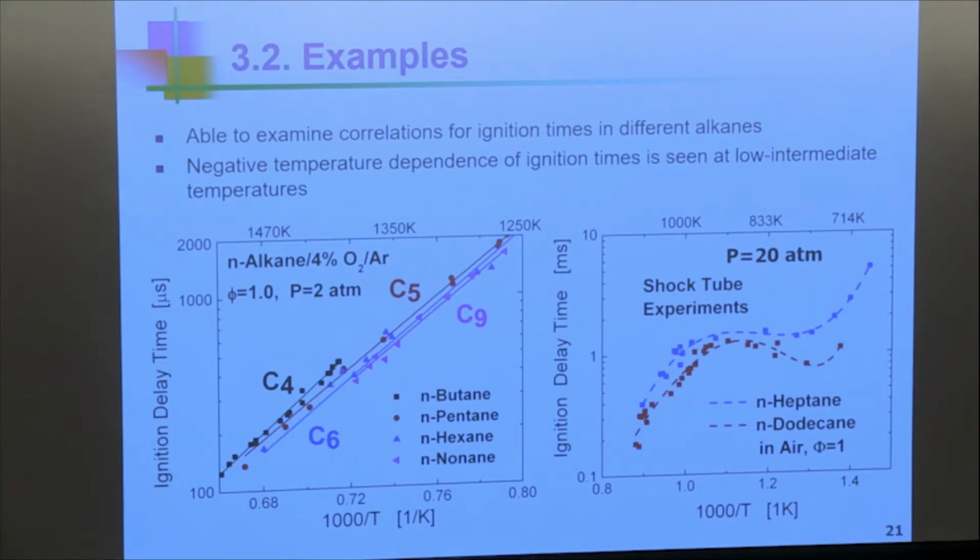But some people would say, well, they're all about the same. So it took high-quality experiments to reveal that no, all of these alkanes, that means saturated hydrocarbons, don't ignite at the same rate. Now that only went down to about 1250. If you go lower, there's something called the NTC region that some of you probably know about. So the ignition delay time has this funny character that it turns over and can even decline before it goes up again. Why does it do that?